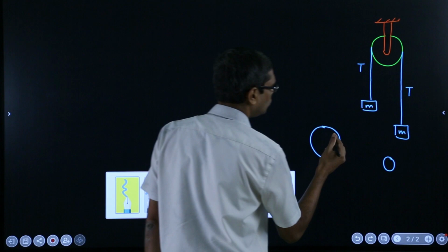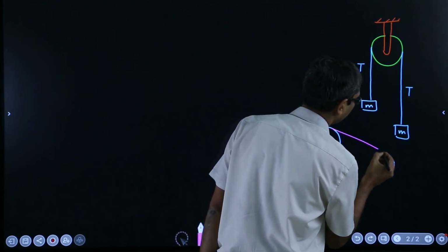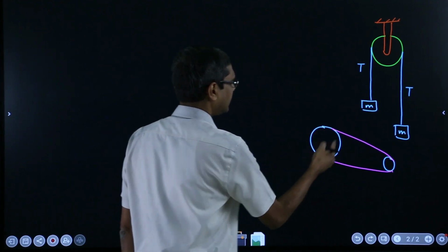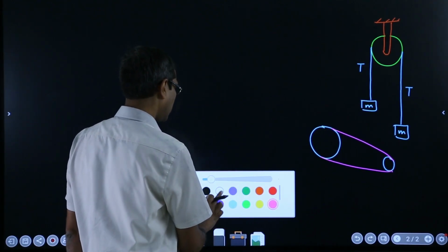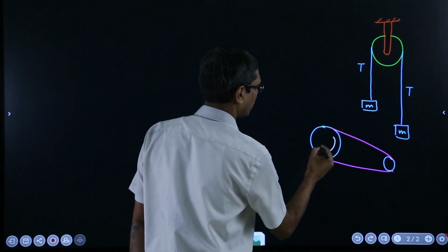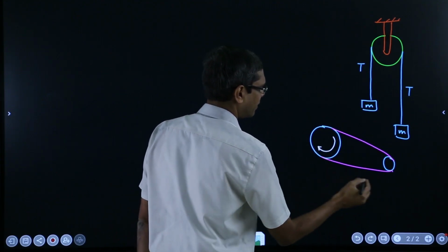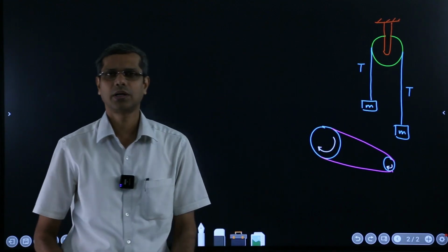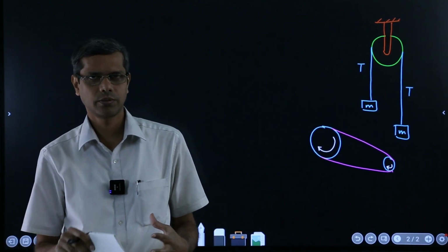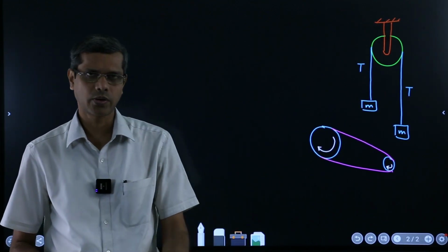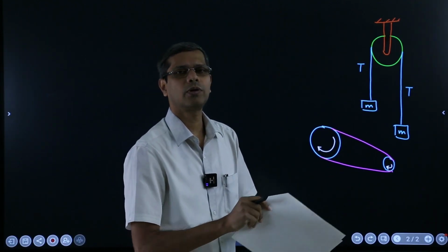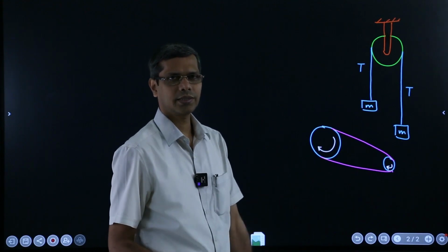point through a belt drive. So you have connected belts like that, and this one is, say, driving. So this one is driving and this one is driven. It's like a gear drive. Gears are used to transfer power, right? And when you have to transfer power over a long distance, generally gears are not useful.